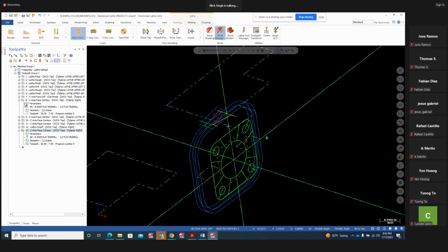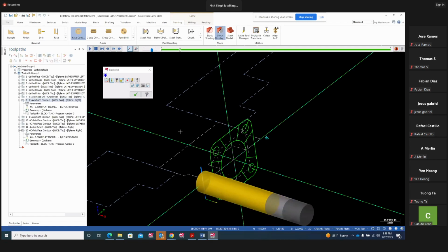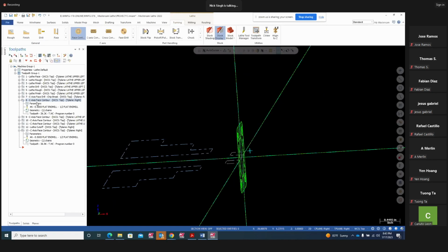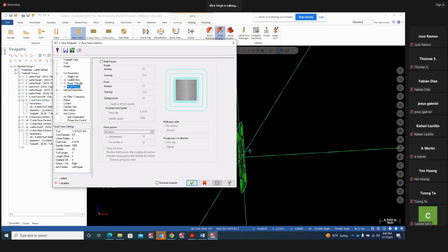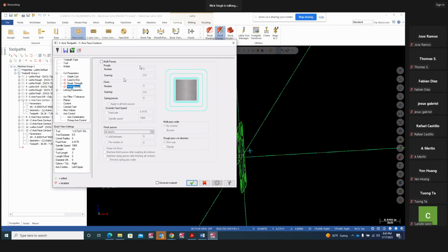And what we have done here on the face contour is right here. This is the same toolpath with a 1/2 inch end mill. Look at this over here. Check out, regenerate, take that out. So on this one we are doing three passes. If you look at here, we are going depth cut, we're going 125 pass, that's fine, multiple passes. This is only one multiple pass, okay.